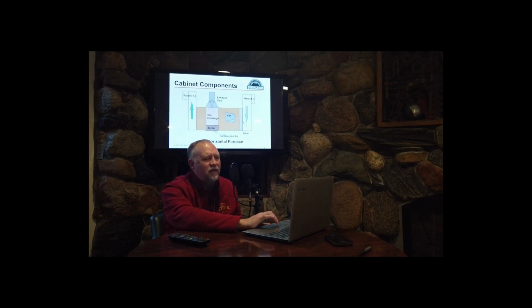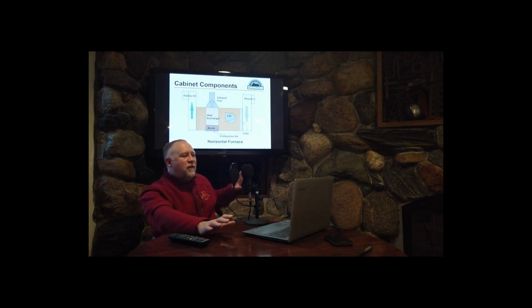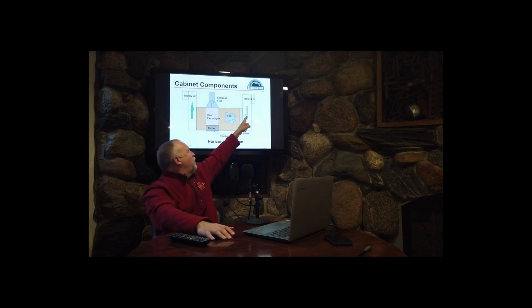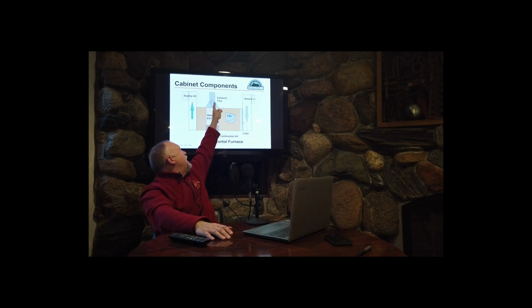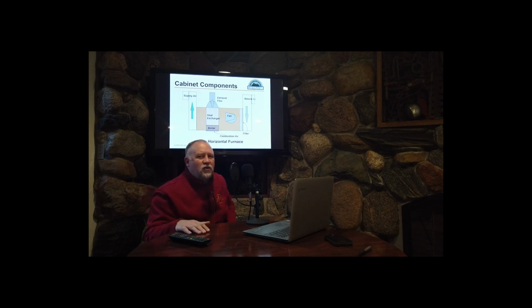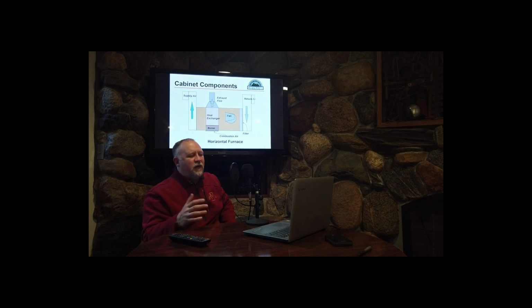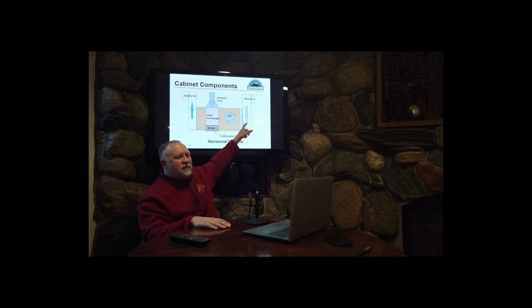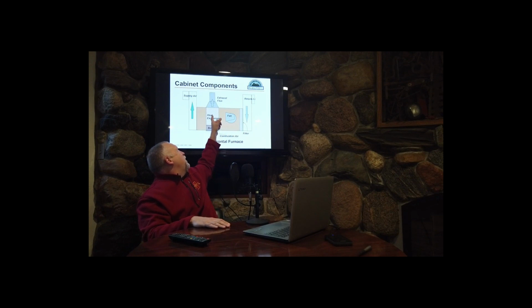Here, I've got a schematic of it on this next one. This is just a schematic. I'll have some better diagrams here in a second. But return air comes from the room, from the house. We have a fan on the furnace that blows it through a heat exchanger. Now, before it hits the fan, we have a simple residential quality filter that filters that return air. I don't want dust, hair, lint, whatever it is from the people space getting on the heat exchanger. I'm going to blow the air through the heat exchanger. All right, the space air goes through the heat exchanger this way.